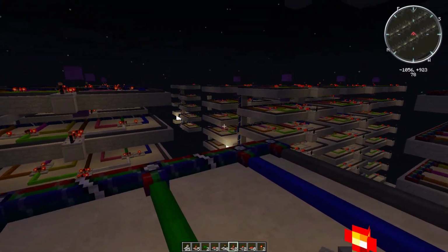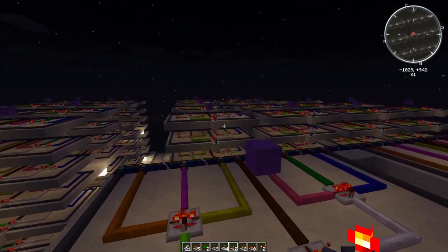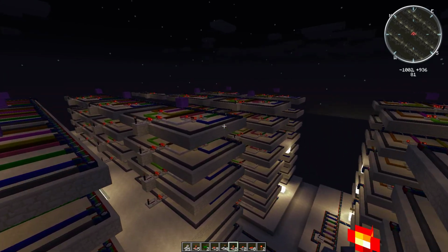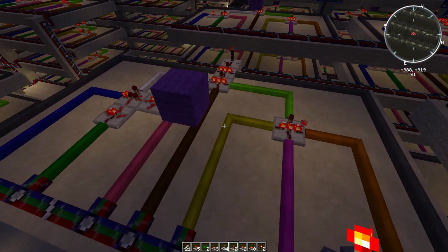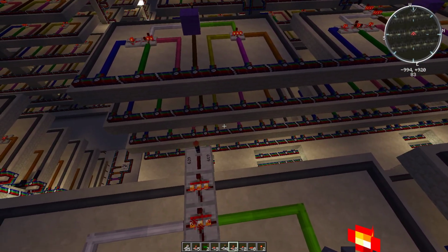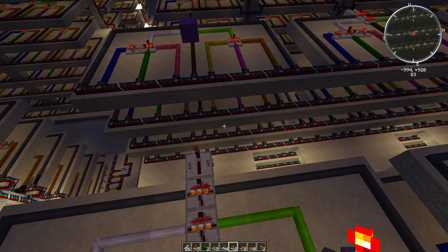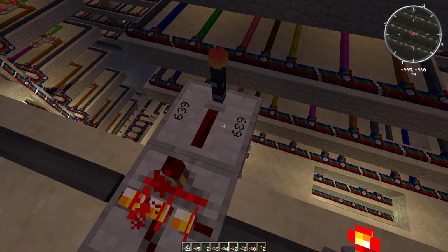Of our data memory, this is pretty much a series of multiplexers, and the data memory pointer will go into these and help select out the location of which byte we want. Essentially, we have these little data transmitters.